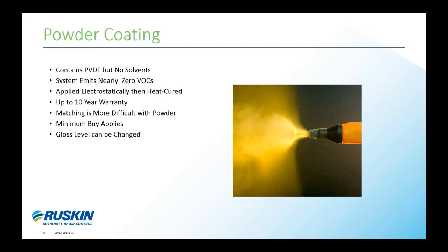If a custom color is required, powder coating is better for a large job because the process to manufacture powder is more difficult than mixing liquid coatings. And also, they aren't necessarily able to match all colors. There's also minimum buys that you'll have to deal with.